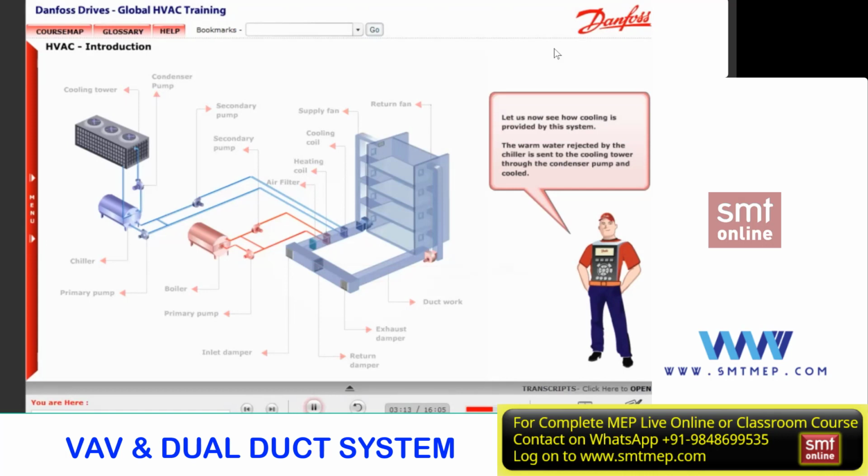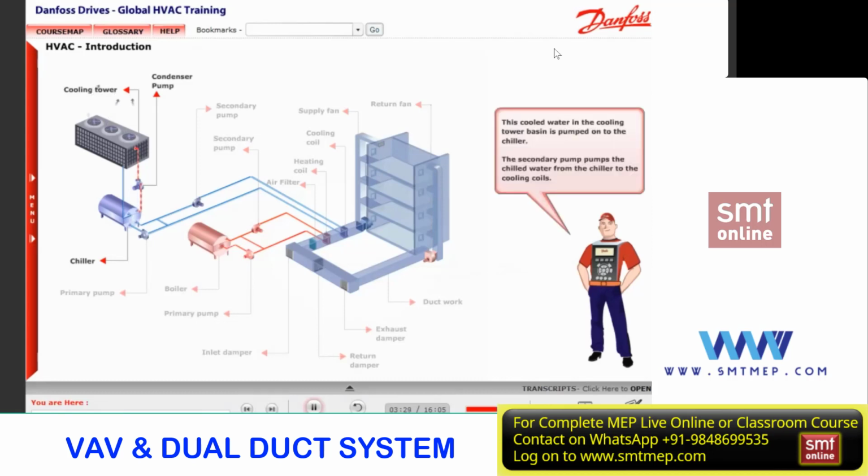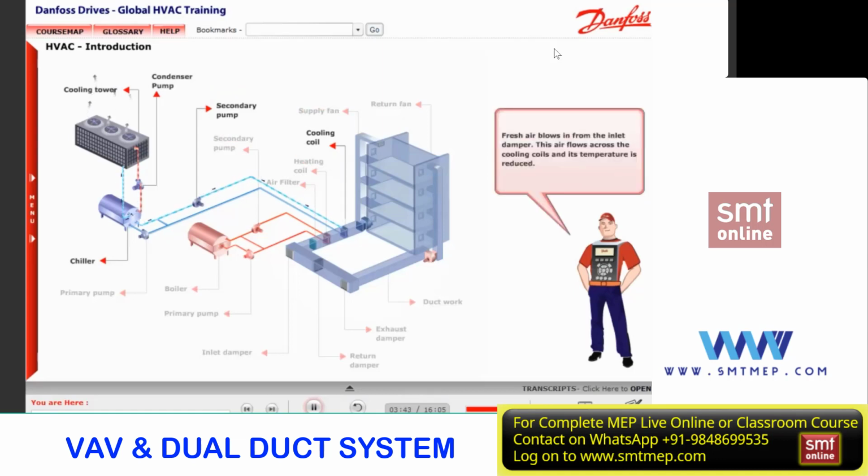Let us now see how cooling is provided by this system. The warm water rejected by the chiller is sent to the cooling tower through the condenser pump and cooled. This cold water in the cooling tower basin is pumped onto the chiller. The secondary pump pumps the chilled water from the chiller to the cooling coils. Fresh air blows in from the inlet damper.